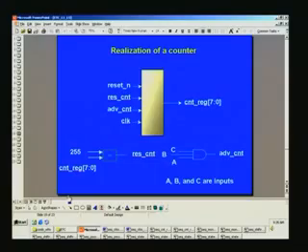We were analyzing waveforms of a counter in the last class, and we will continue to do the same in this one. As you see, a counter has a reset input, and there is further a reset count here, which will take place only when counter reg, which is the running counter, is equal to 255. This setting point can be changed if you wish.